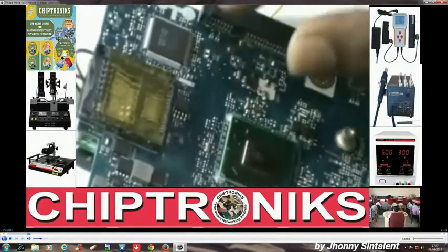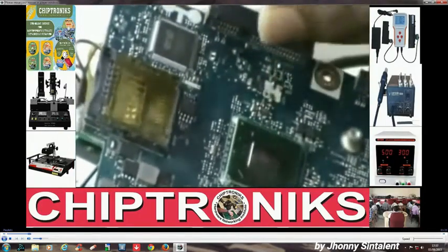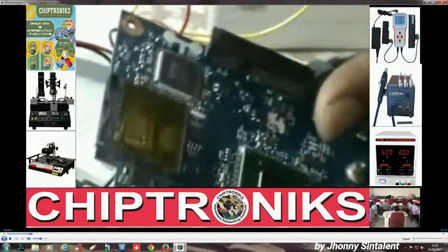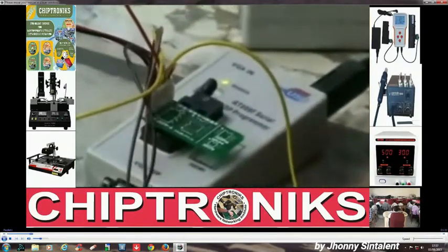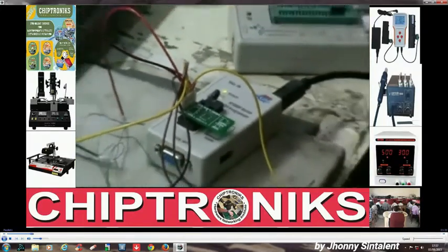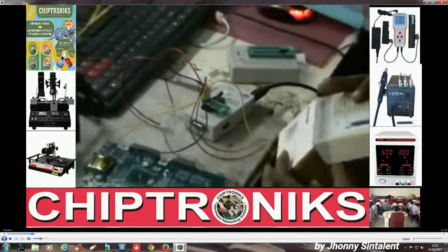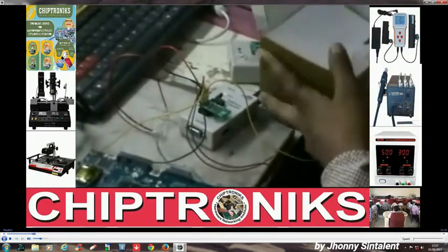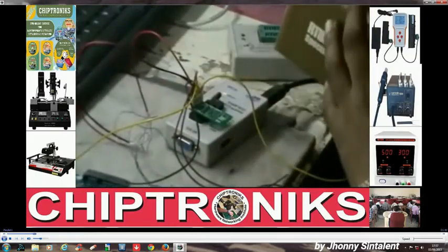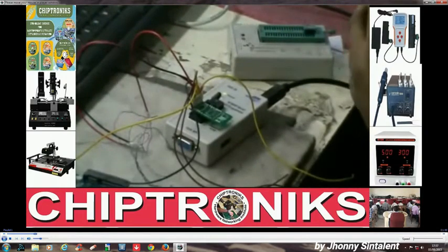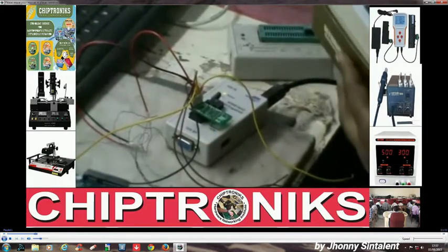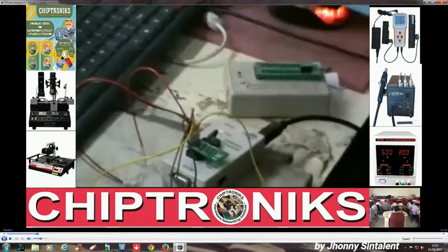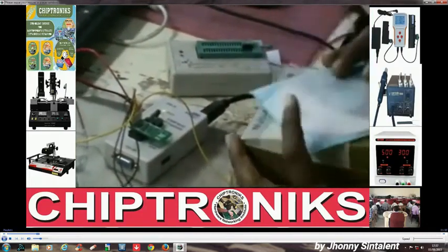whenever we need to desolder or resolder a new kind of IO controller, we need to flash the embedded controller. For this we require a special BIOS programmer, and with me I have the RT809F. This is the only commonly used BIOS copier in today's world which can program this IO. The RT809F comes with this copier and this ISP module, and with some CDs.